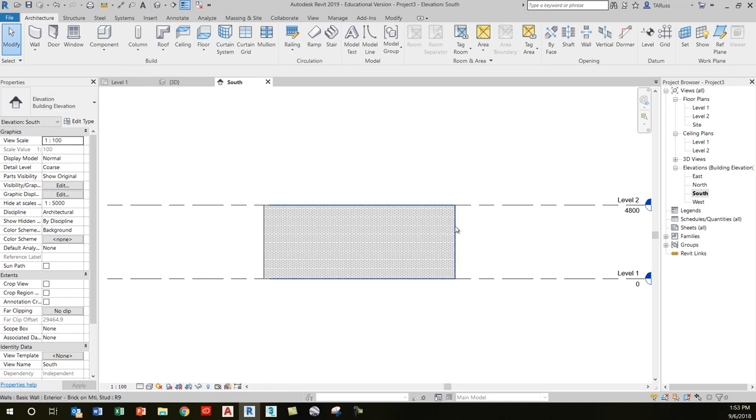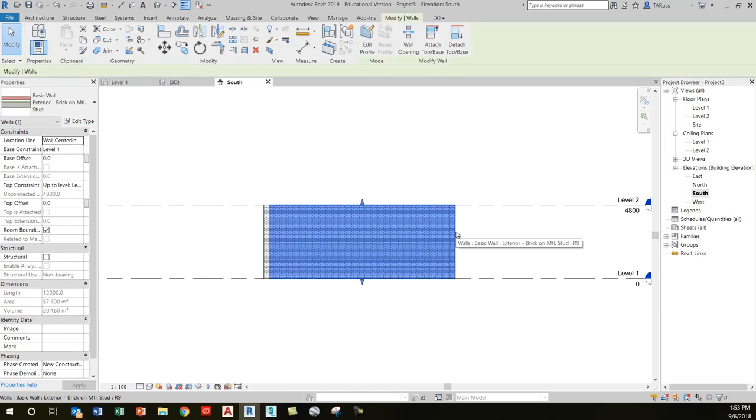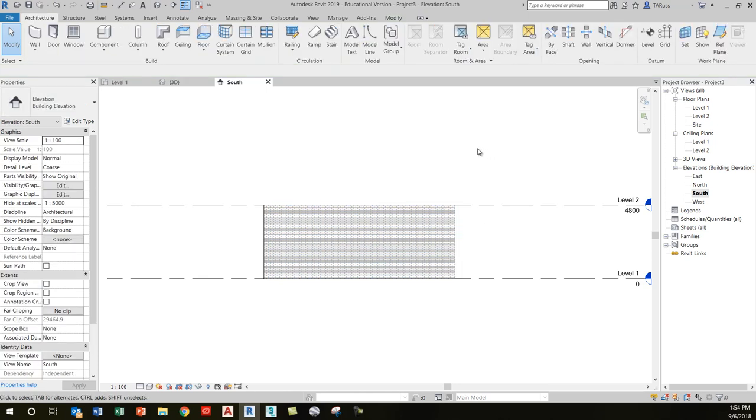As you hover over an object, you'll see that its edges take on a blue highlight. So that's just giving you a little prompt about what it would click and select if you were to actually press your button. And then once you do actually click, you'll see the whole object take on this blue highlight. So just pay attention to that blue temporary highlight in the initial stage, and then the blue highlight the whole object takes on once you've actually selected the entire object. And that's just a basic look at how we do selections in Revit.